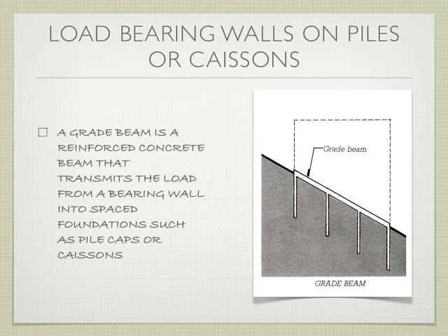Okay? So the top surface of the soil, that was all that nasty clay, could expand and contract independently of the friction that was actually holding the building up down deeper in the earth. And so when you put all of those together, you have a building that's incredibly stable and consistent. We did this project 15 years ago, so it's been a while. And if you go back in the building today, there's not a single crack in any of the doors. There's no settlement. It works as a complete unit, rather than any kind of differential settlement. And it's in a soil that is notorious for moving around, right? But these are consistent. So there are ways to get around it, which is what's important.